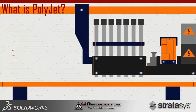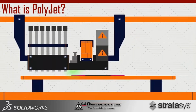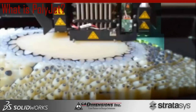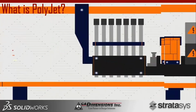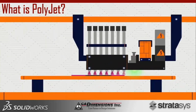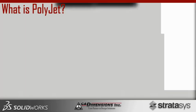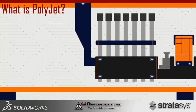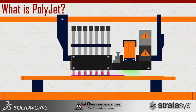Instead of a spool of filament, you have material jetting happening. So essentially there are canisters of this liquid photopolymer that are then sprayed out into a mist or dot matrix of various materials, similar to an inkjet printer, which then has a rolling mechanism coming over each layer to smooth it out and flatten each layer to resist bubble buildup in the parts, to make sure they are as solid and consistent as possible. And there are also two lights that follow the movement of the head at any given time. So instead of having a partially cured part that you would see with an SLA system, for instance, the parts that come off a PolyJet system are completely cured right off the printer.